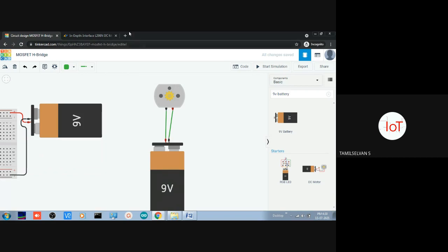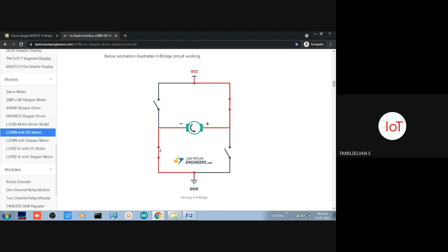So what you can do is, instead of switching like this with manual wiring, I'm going to use this particular H bridge circuitry. Okay, the main aim of this H bridge circuitry is to provide the voltage power supply in both directions. Whenever it is required, it will be controlled accordingly. Okay, say for example, for one particular moment of time it will be going in the positive direction, and at another moment of time it will be going in the negative, anti-clockwise direction. Okay, so for the clockwise direction movement, I need to energize this particular switch. Okay, so you can see this particular switch has to be energized, and this switch as well.